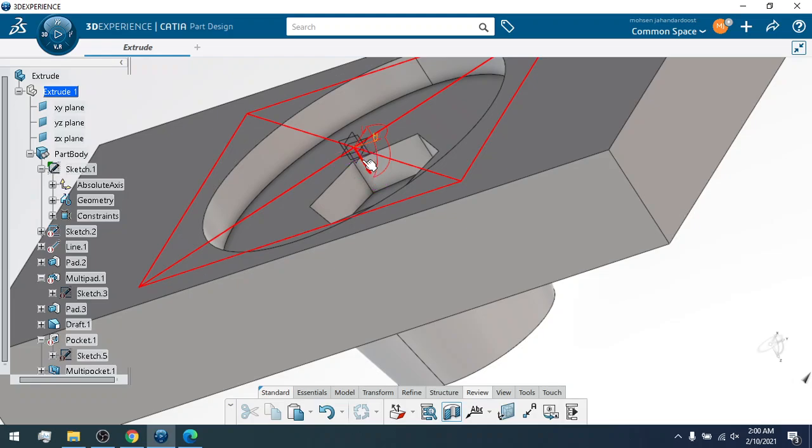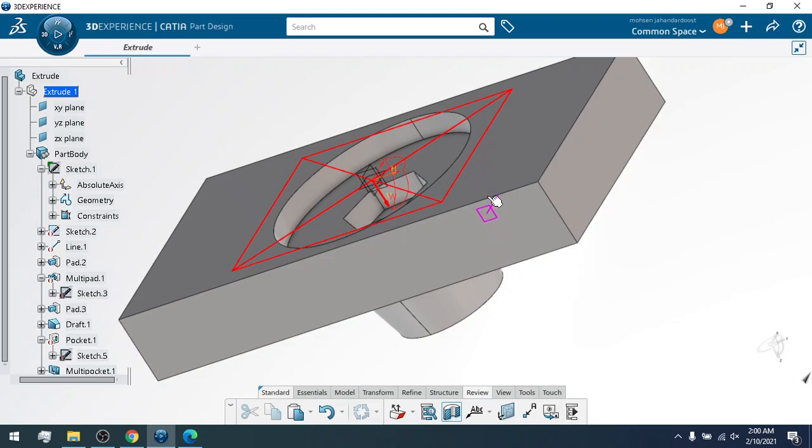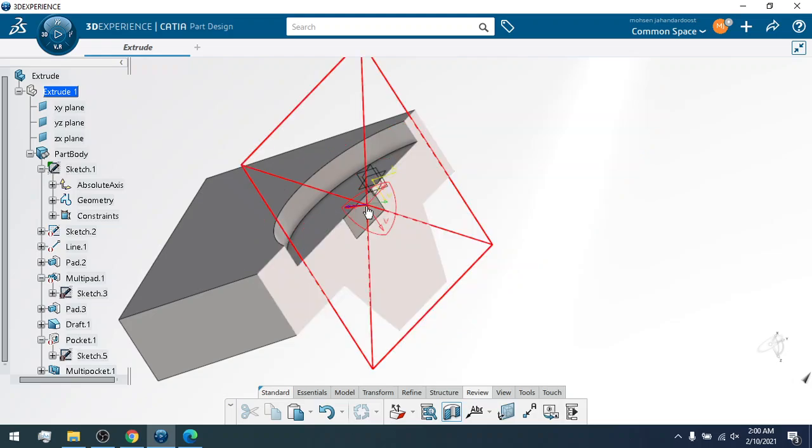Right now just select this blue line. The blue line that you can see with the direction shows the plane that you want to select to put the cut plane. So you can see that I can move it. If it's a circle, you need to keep the control down, and then it selects only the point.